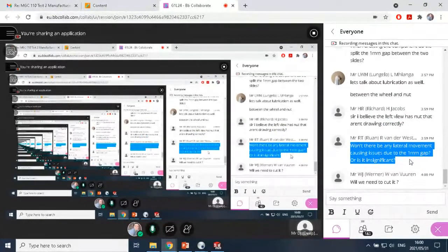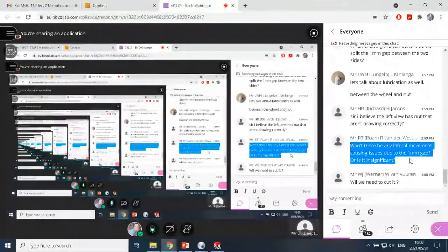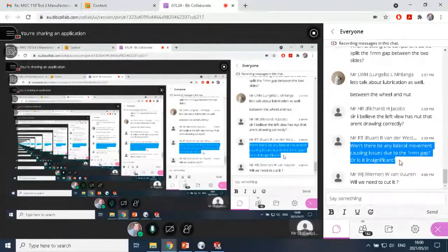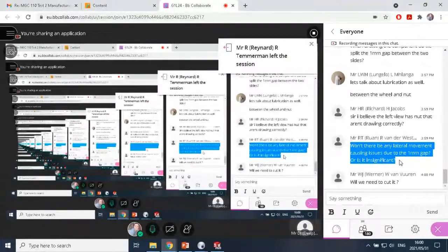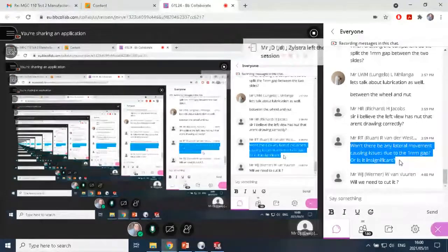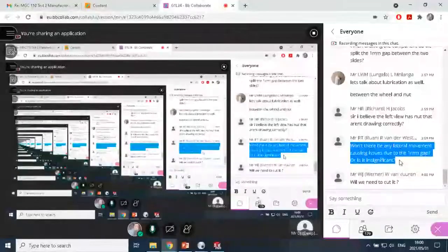So typically you'll design the system such that the lateral movement is not a problem. So in this case it would be considered insignificant. What is super interesting though is motor car engines. The big rotating part of a motor car engine called the crankshaft, even that thing has slight axial looseness on the engine. Otherwise, as the engine heats up, the bearings will clamp down on the crankshaft. Typically, they have little thrust bearings called thrust washers, which actually take up the axial forces that your engine has to undergo.